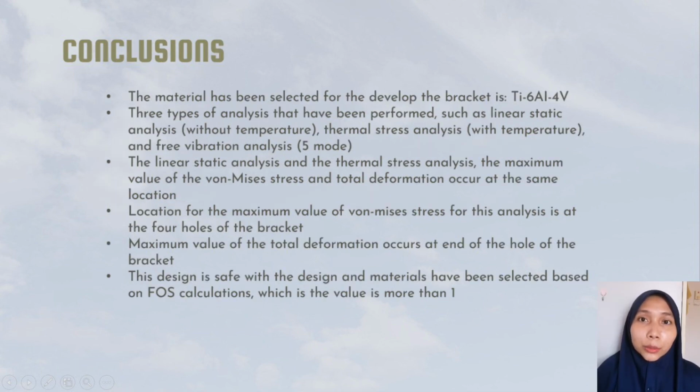Analysis has been done to look into how to make a new geometric mounting bracket from a new material called titanium alloy. Three types of analysis have been done: linear static analysis without temperature, thermal stress analysis with temperature, and free vibration analysis in 5 modes.